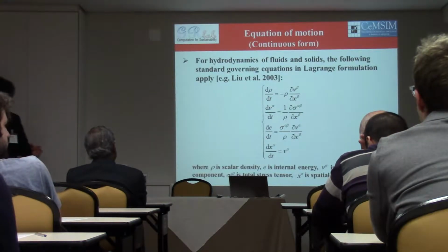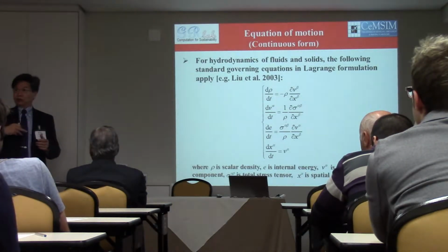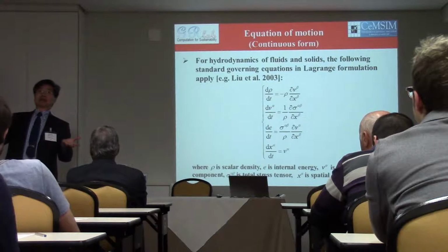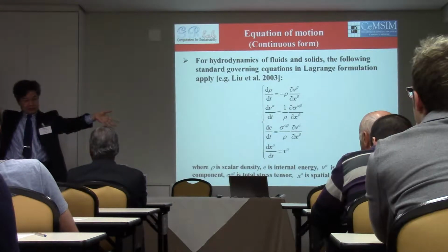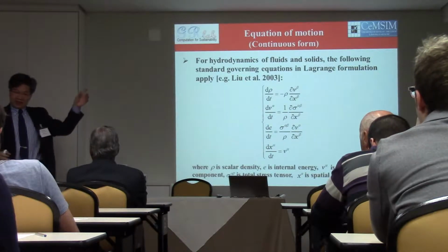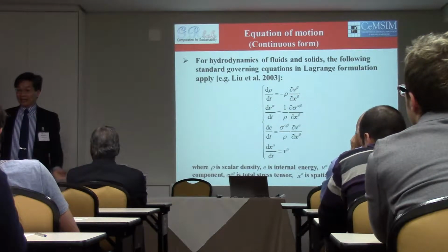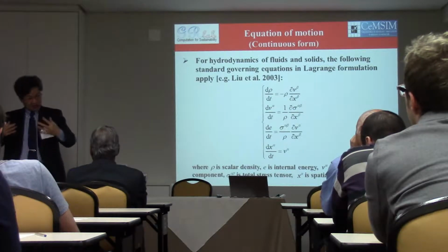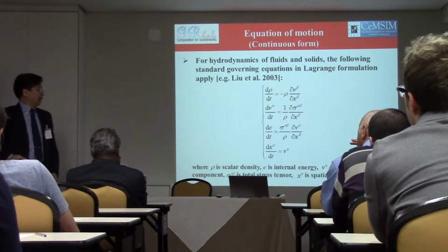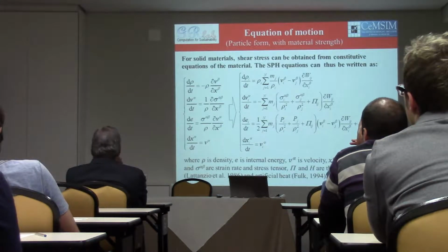Now, I mentioned earlier, SPH is good for CFD problems, but then we simulate, say for example, the effects of detonation of a whole building. So the building is going to break into pieces, right? But they are solids. They are not fluids. Okay? So in SPH, they actually treat this kind of phenomenon as a fluid. Okay? So even though they are solids, the flow of the debris basically forms a flow. And that is the idea that we can use SPH also for solid mechanics problems.